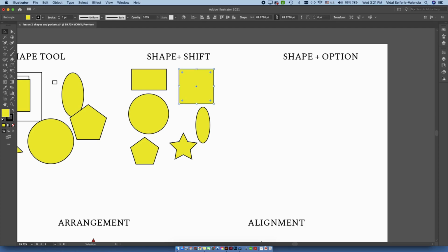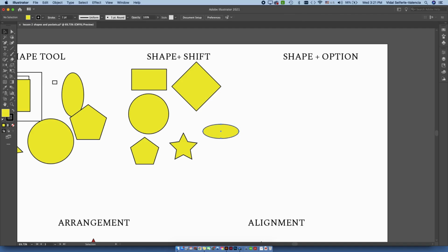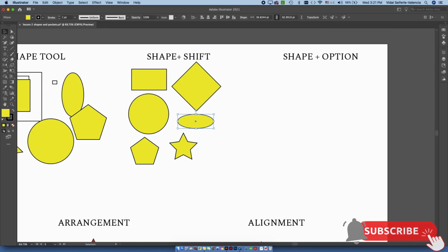And additionally, if you utilize any of these transform tools, so when you see I select this rectangle, there's these little 2 arrows around the corner. This just allows me to freely rotate the shape. But if I hold Shift, it will constrain the rotation to 45-degree angle axis rotation. So it's always going to rotate on a 45. So the Shift key is super, super useful and is something I'm using all the time, so it's good to get familiar with utilizing it.